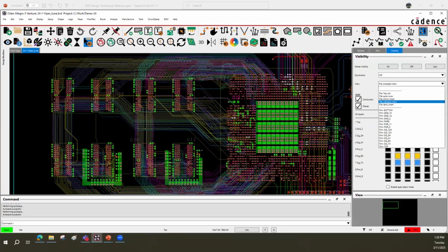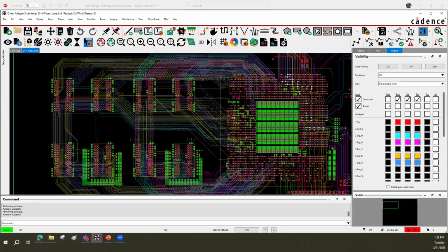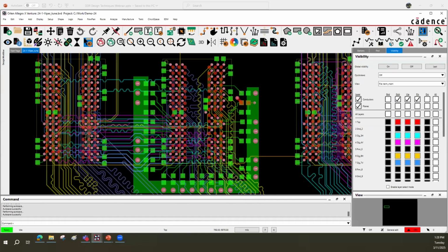Let's go ahead and then talk about our termination on there. It's important, as you can see on the far left here, I've got my capacitors, and I'm trying to get them as close to the pins as possible. And then outside at the very last chip that I have, there's my termination. Now, what I've done in the past, and I found it to be very beneficial, is to route all these first.